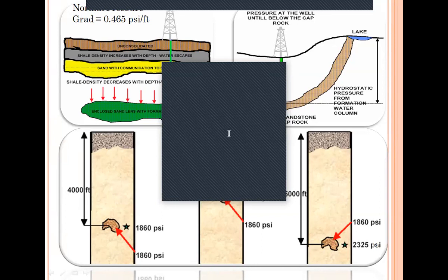When drilling, we should always have, as I told you, Alberto, hydrostatic pressure just greater than the formation pressure. It's normal to have a 100 to 200 psi margin. Maybe we have more if we want to increase the mud weight just to avoid the caved shale, to maintain inhibition for the shale. So maybe we increase the mud weight if we have caved shale on the shaker, as we saw yesterday. But this is normal, 100, 200 psi.